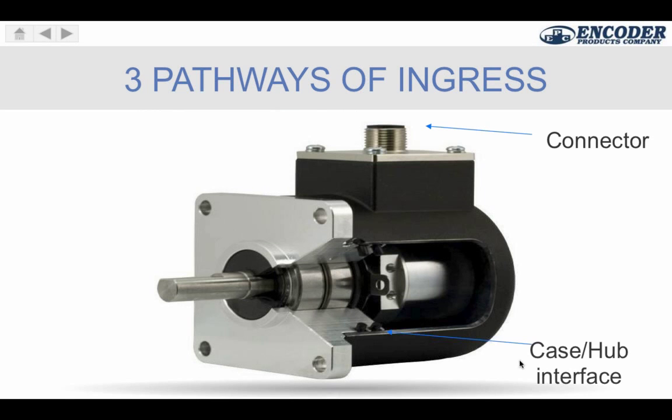And remember also there are 3 pathways of ingress into the encoder: through the connector, the case and hub interface, and the shaft seal. Sometimes manufacturers do not always list or consider all 3 routes of ingress when they apply a rating standard to the encoder. So be sure all 3 routes are covered by the rating.